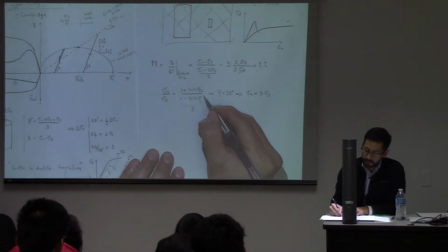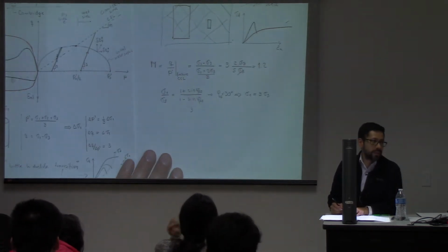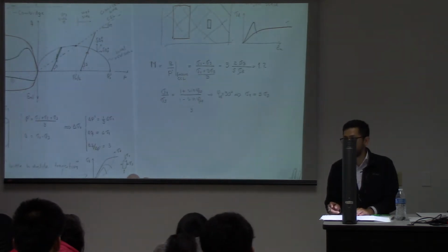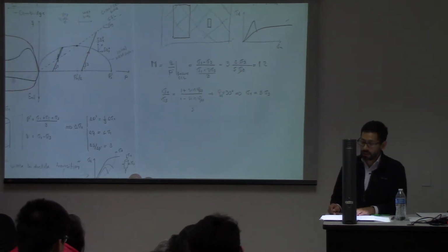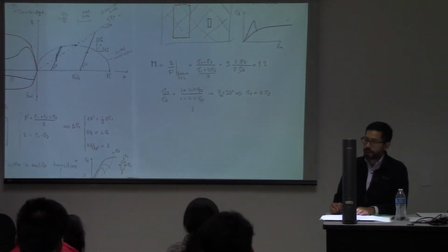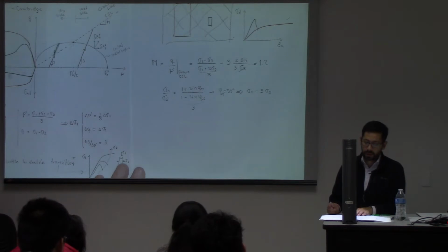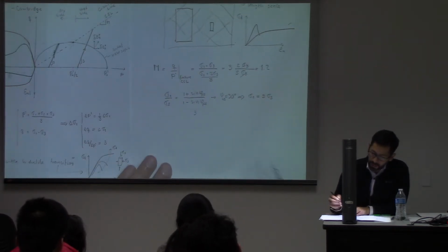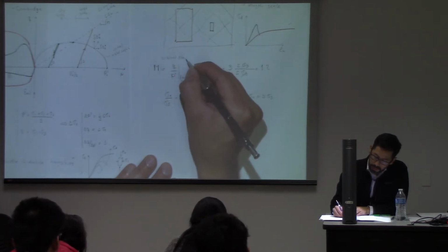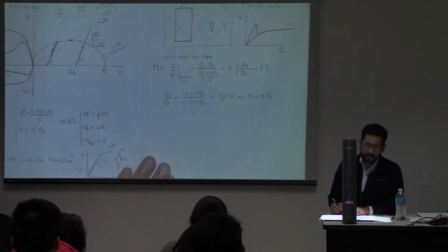And now I'm going to add this CS over here. And if that critical state angle is, say, 30 degrees, then your M is solely a function of that. And in this case, it's 1.2. But if you had some other friction angle, you will have to do the same operations in order to get the value of M. But M is basically a friction parameter. Okay? So then M is related to the critical state line slope. All right. So we have that one.